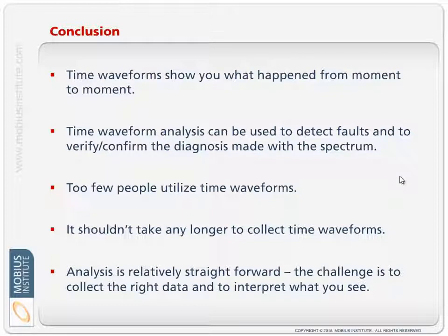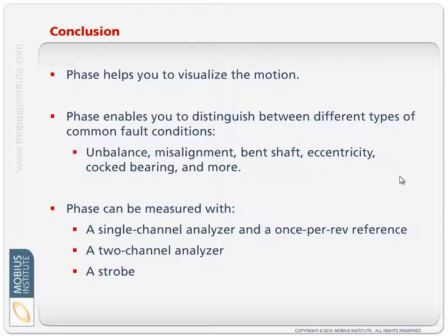Not enough people use this tool. I've heard all kinds of excuses, and I don't mean to offend you if you're not doing it. Bottom line is, it's not hard to measure it correctly, and if you do measure it correctly, it's a lot easier to analyze the data. It shouldn't take you that much longer, but when it helps you, boy, what a bonus that you've got that information. Now, phase, on the other hand, helps us to understand the motion of the machine.